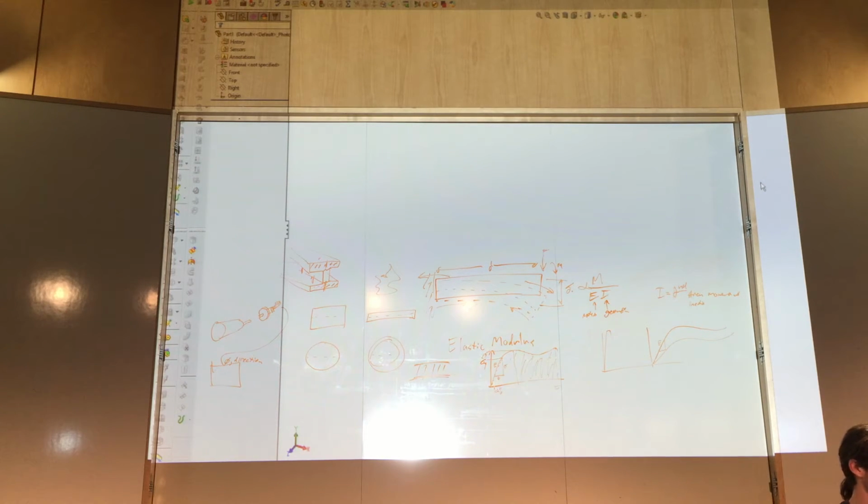But other ways to do it are you add compliance. Like on this little thing, it's still real junky, but I put rubber sleeves on one side of the shaft so the shaft can move around and I'm not binding it up as it goes around. So I've got my constraint along this axis, and then this guy's providing constraint on this axis.